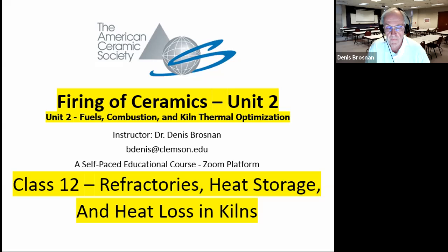So today, we're going to the next component of a kiln, and that is to look at the refractories, the insulation in the kiln, because we not only have to provide the heat, but we obviously have to contain the heat. And if you get above a few hundred degrees Fahrenheit, we're not going to be able to use carbon steel.